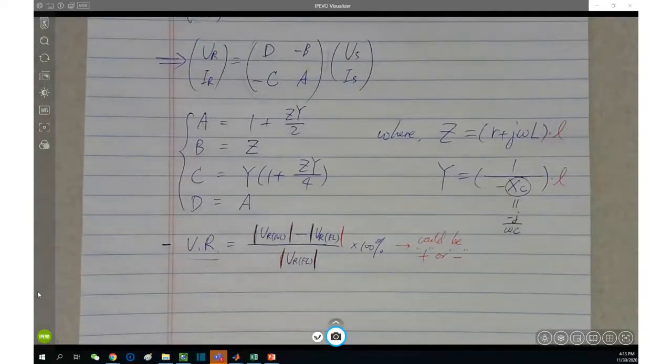Okay. You are feeding capacitive load. That's absolutely the resultant voltage is actually increased. It's absolutely possible. And this is also something you recall in the power system, we always need a capacitor bank, right? The capacitor bank is essentially for what? For providing the reactive power to the transmission line.